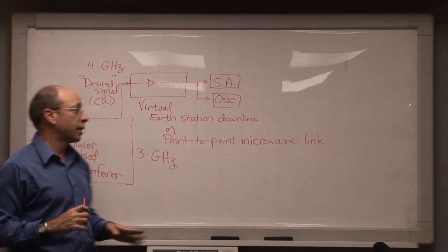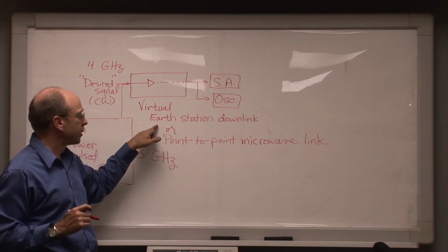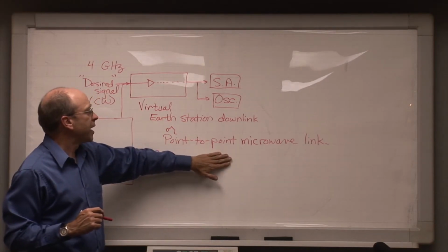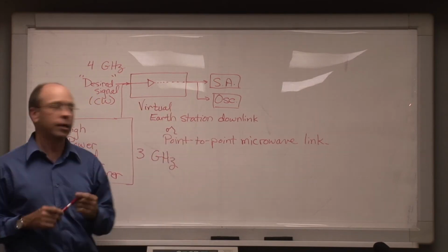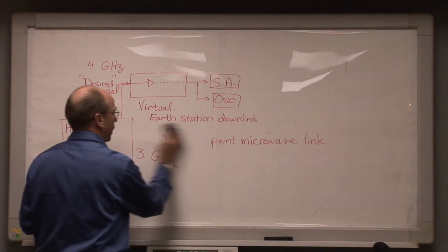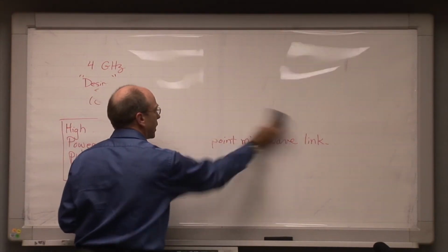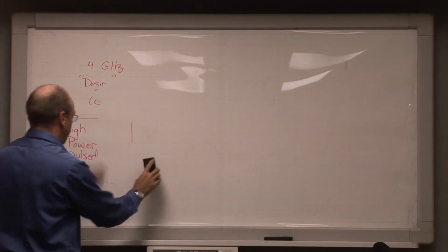They become concerned. It can also cause significant data dropouts depending upon how vulnerable the digital data protocol is to the interference, which, to sum it all up, makes the system more sensitive, not less sensitive, to the effects of the interference when it occurs. So we actually saw an increase in the number of reports and the complaints about the effects of RF front-end overload type interference back in the early 90s.